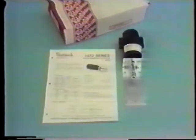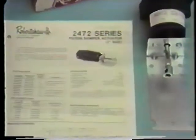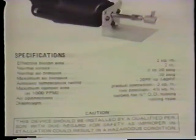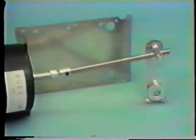Another factor that must be considered in selection would be the type of application, either two-position or modulating. Detailed sizing information can be found in the individual product data sheets. Shown here is the right angle mount, one of 2 common mounting styles. This type of mounting provides a rigid mounting method for the actuator. The actuator shaft is connected to the damper by ball joints, a push rod, and a crank arm.